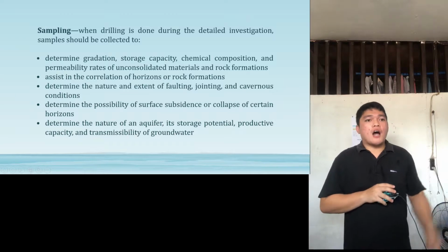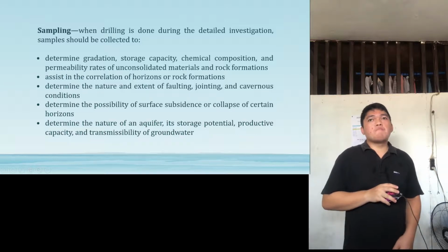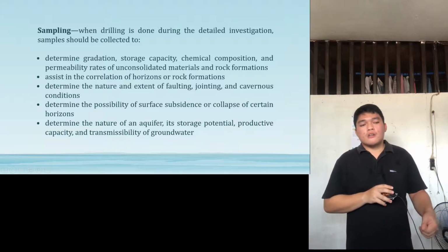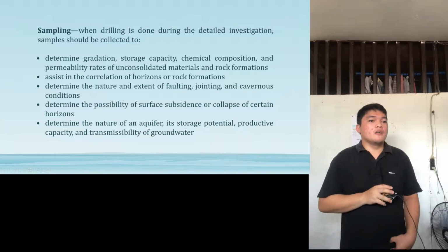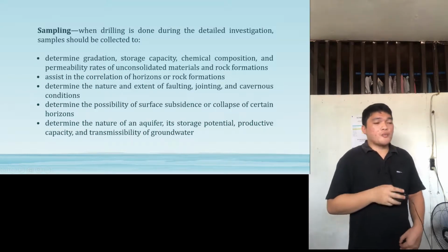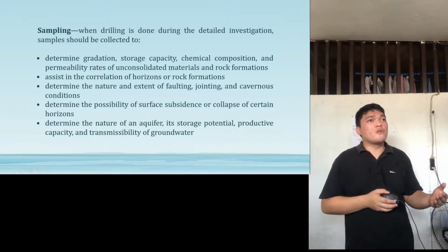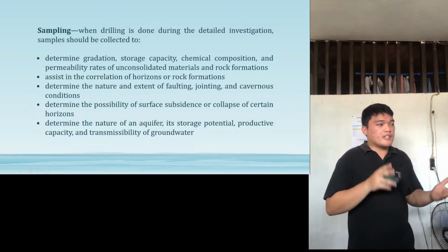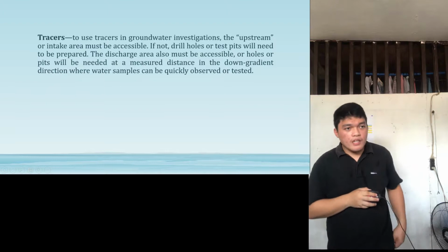So, after drilling, we will collect samples from our drill site to determine data like gradation, storage capacity, and the nature of an aquifer, its potential to store water. So we know what an aquifer is. It is like a storage area of water in a certain land. That is an aquifer. Next, tracers.